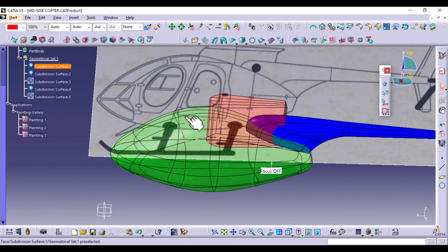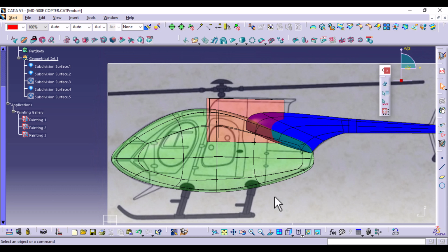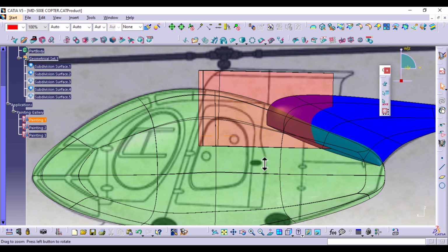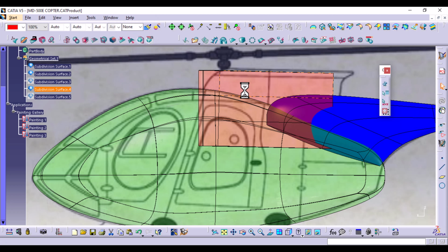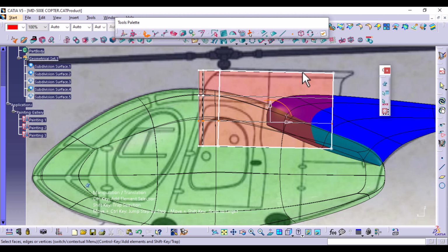Now we need to create the top curvature. So you can switch to the right view. And we're going to add one more section, 1 or 2 per se. Select on face cutting, subdivision 4. Let's drop down this to 2. Click apply and exit. Now what we want to do is to push this a little bit to the side. I might have to raise this once again.